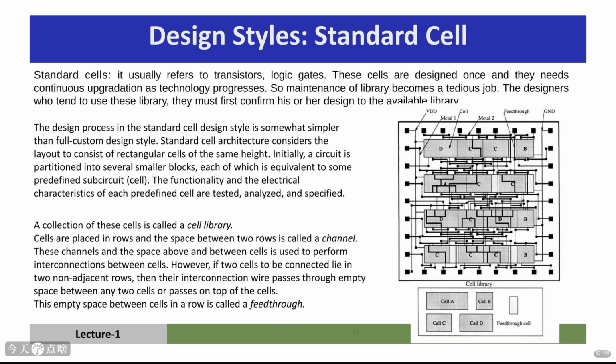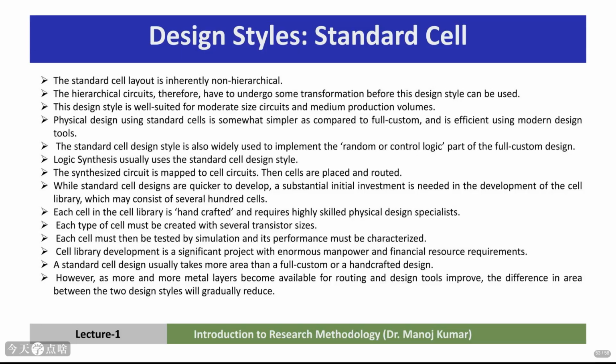The diagram shows a cell library with different types of cells and a feed-through cell used for routing between non-adjacent rows. This approach simplifies the design process compared to full custom. Standard cell design is inherently non-hierarchical, so hierarchical circuits need transformation. It's well suited for moderate-sized circuits and medium-volume production. Physical design is simpler than full custom, especially with modern CAD tools.